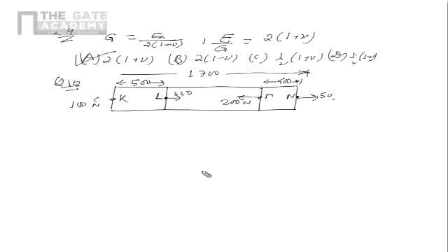What we are supposed to do is find the total change in the length of the rod due to this particular loading. Obviously the load is not uniform across the segments, and the lengths are also not the same, so we have to find the change in length of each segment separately and then add up the three changes in length. That will be the total change.